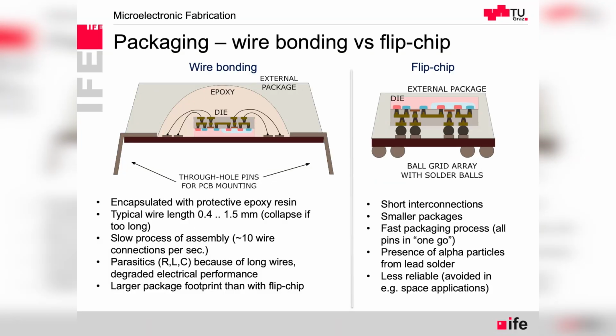Then other than bond wires, there are also packages that use the so-called flip chip. Later, from outside, when we take several different packages, if they have a ball grid array, for example, at the bottom, then most likely it's a flip chip. They tend to be very thin, and unfortunately also much more difficult to realize from the reliability point of view.